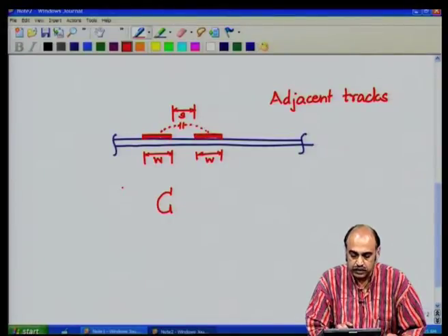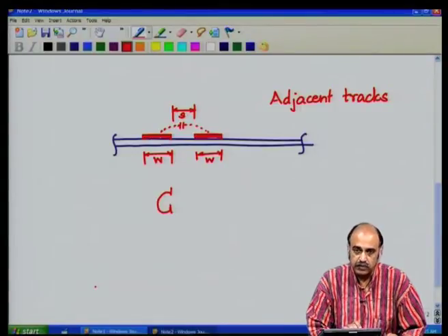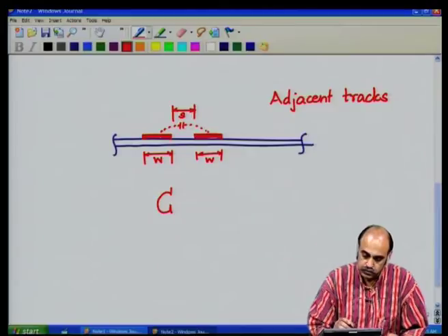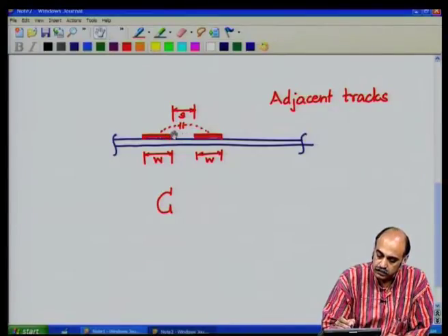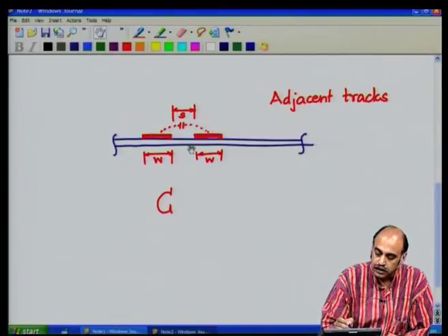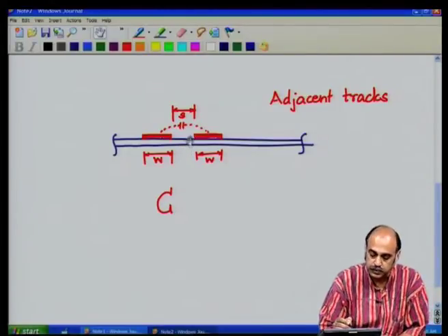Then you have the spacing S, and then we need to find what is the capacitance. You see that you have air as the dielectric here. In these spaces, you have air as the dielectric, and the distances are not constant, they keep varying. And then you have the laminate material itself as a dielectric. So, it is a mixed combination and difficult to have a closed form solution.